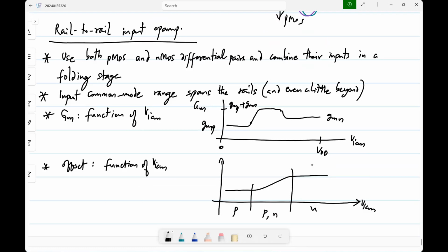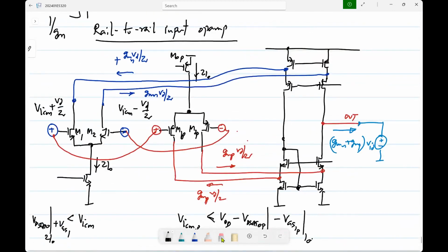No, I mean, there are ways of using both NMOS and PMOS, but this is not really giving you any advantage, right? That is, you have both NMOS and PMOS, but you are burning separate bias currents in each of them. If I had a bigger differential pair with a higher current, you would also get more GM. So that way there is no advantage in this.